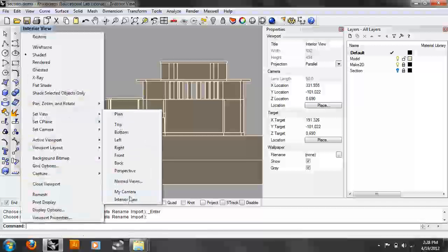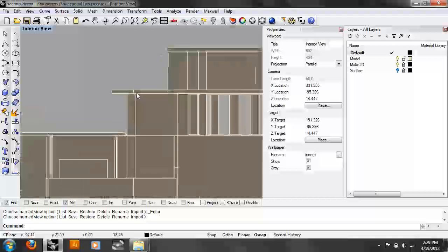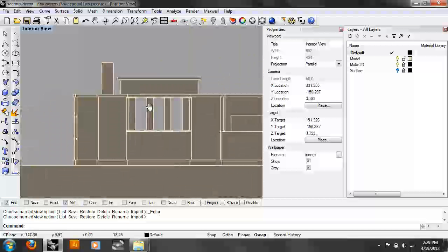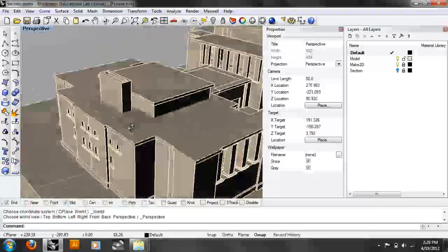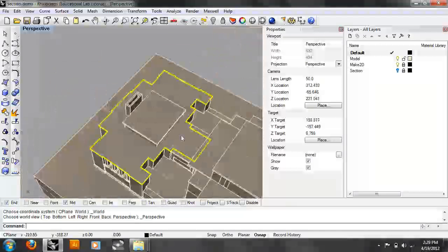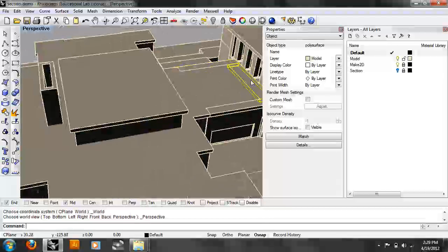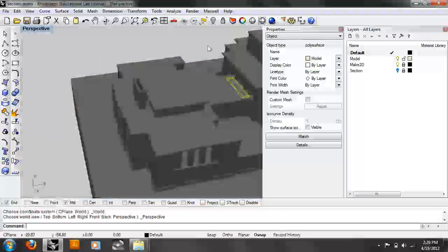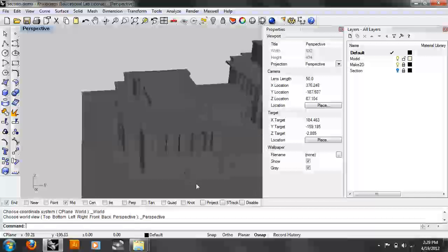Do you think that model was built by extruding planes? Yeah, if you look at the sides of things, there are these seams in it where it wants to be one piece. There are things sitting inside of each other. That's because the exterior walls were extruded and then the interior walls were extruded. Some of the roof lines, they just added these squinch pieces in. It's not great. It's okay. If you render it, you don't really notice the difference, but it is not clean. It would be hard to fab this, let's say.